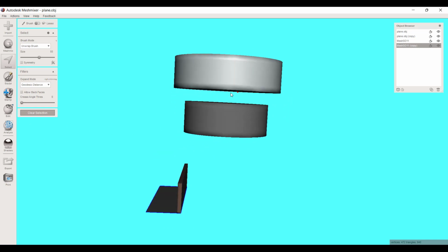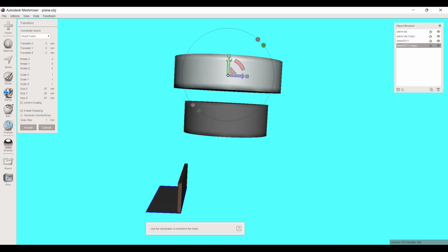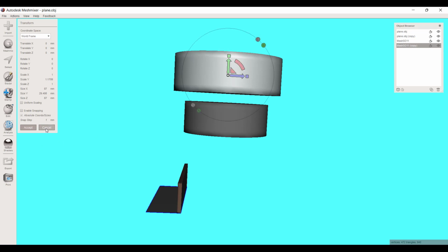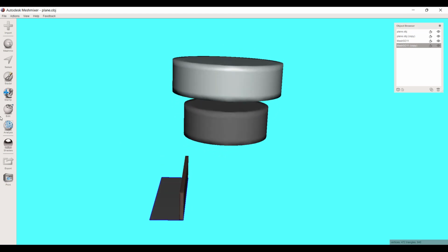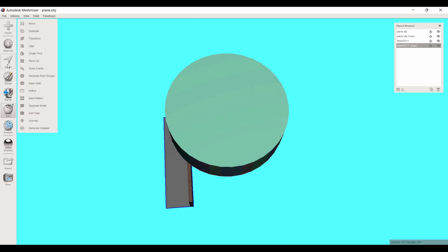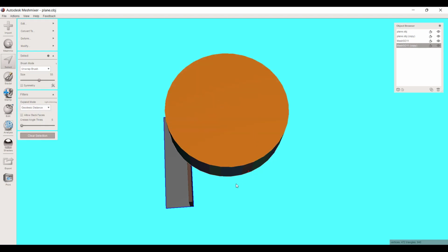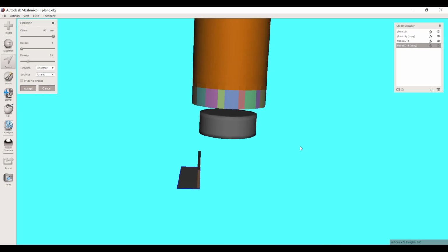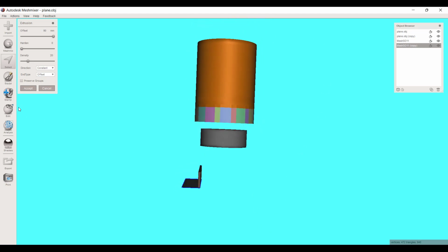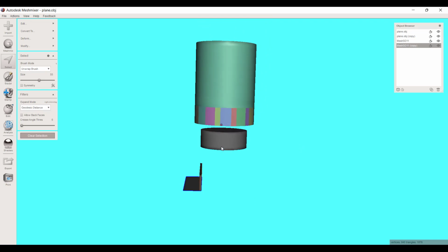I've used my scaling and everything to maintain these dimensions, and if I go and now transform this shape and stretch it, now I'm losing that orientation of that tapering zone. So what I'd rather do is just take this top flat edge and just extrude it upwards. Easiest way to do that is under Edit, generate some face groups. All right. Any kind of a big flat surface is going to be a single face group. I'll select that and hit D for extrude, and I can just extrude that up. I don't know how tall the bottle is, but let's just say it's 90 millimeters. Okay. So now you have something a little bit more representative of a bottle.